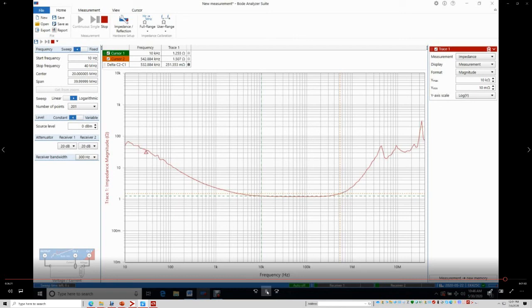It's the dominant one. Then as it sweeps, you have the ESR of the capacitor and probably a little bit of the control reducing this. So this would be the ESR of the capacitor, and then as the impedance rises, that is the series inductor, which then becomes the dominant impedance looking into the power supply. So here you have a nice representation, a good measurement.